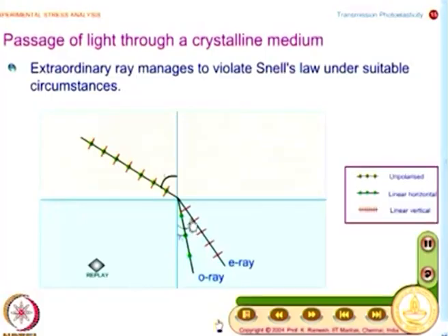And when I have this angle change, I have R2 and R1, what do you infer? You will say refractive index is different. That is not sufficient for me. When I go to photoelasticity, what will I have to look at? I look at refractive index as different velocities. So, that gives you the information.